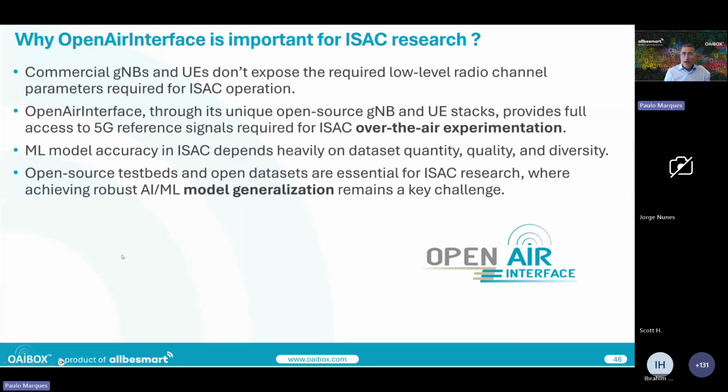Okay, now why is OpenAirInterface so important for ISAC research? Because commercial gNBs and UEs don't expose the low-level radio channel parameters required for ISAC operation. OpenAirInterface, through its unique open-source gNB and UE, provides full access to the 5G reference signals required for ISAC over-the-air experimentation.